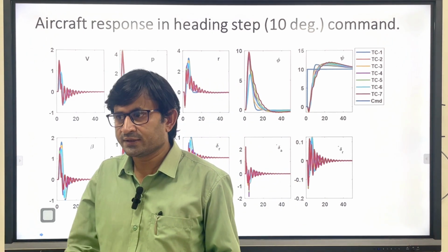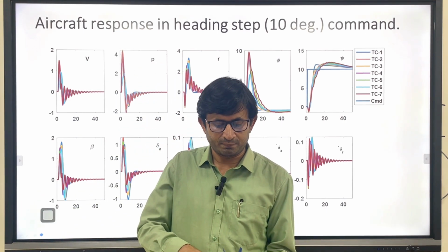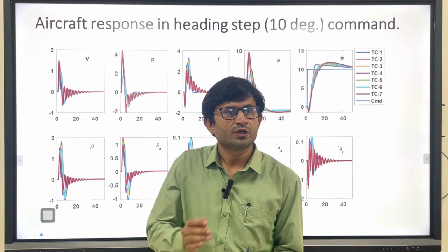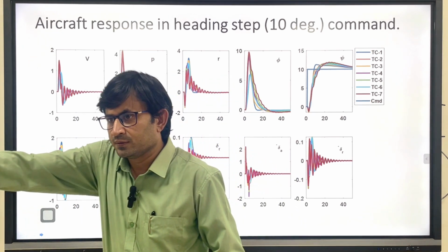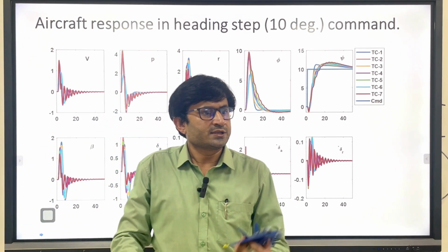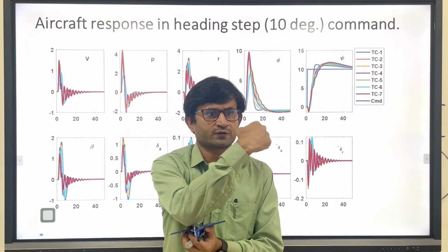Side slip angle, I already explained to you, is what the relative airspeed makes with the plane of symmetry, that is nothing but beta. So every time you have to make a turn in such a manner that you are in a perfect circle. And since when you bank, there is a lift component, L cos phi and L sin phi.